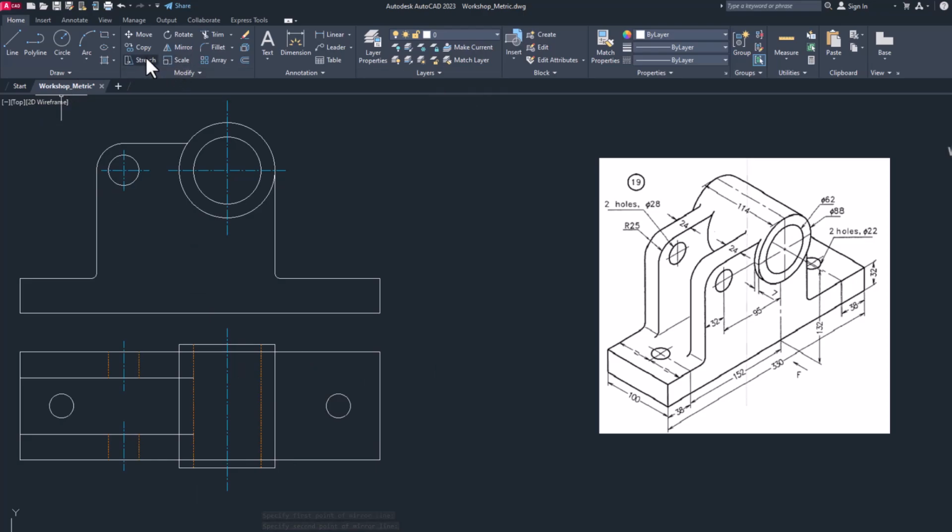Instead, I will copy these two center lines. Right. So it will save my time for this individual circle. Okay. Now let's draw the center line again. So from here, let's go up. Now let's try to complete the hidden part of this small circle. So from here, this is 32. Similarly, from here, this time I'm extending and I will trim out like this and this. So this will take a little extra time.